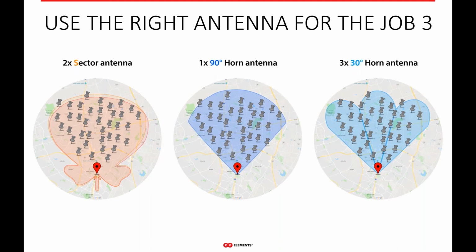With horn antennas, you can either use a lower gain, wider one, let's say if they're really close in, or if you need higher gain for more distance, you can use more narrow horn antennas to cover the same area, and not use as much down tilt on each, to get you the AP capacity you need without having the beams overlay each other, which again causes huge issues with today's Wi-Fi chipsets. So understanding this before you deploy is really important as well.